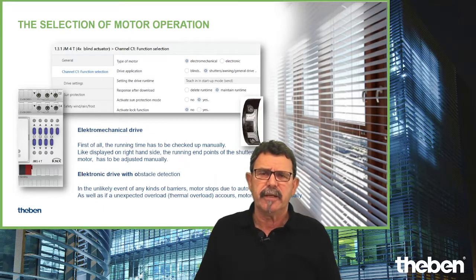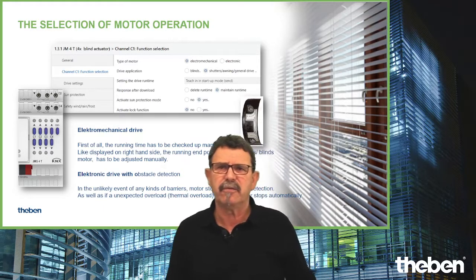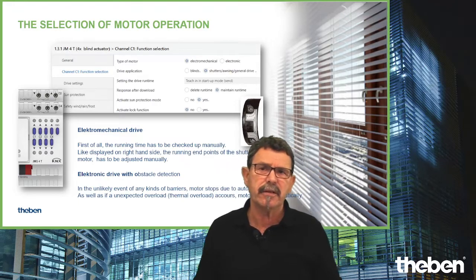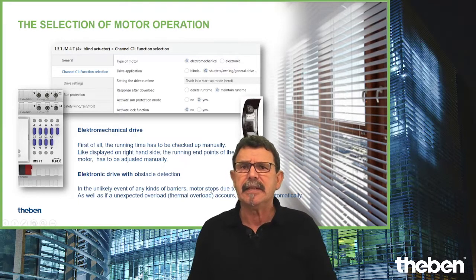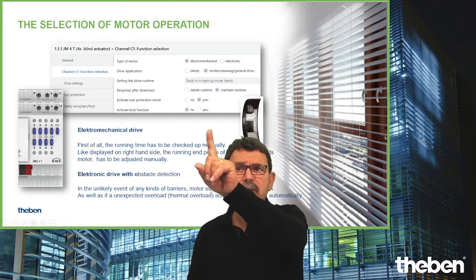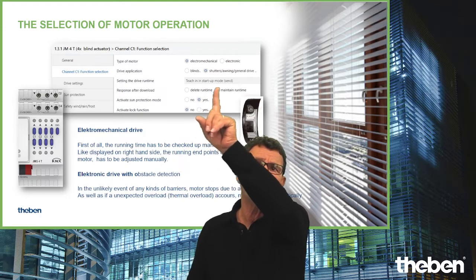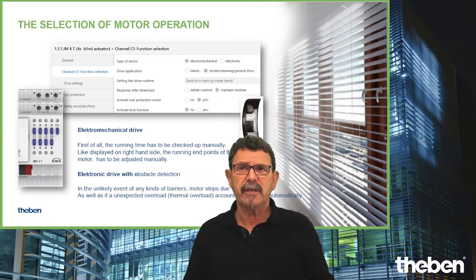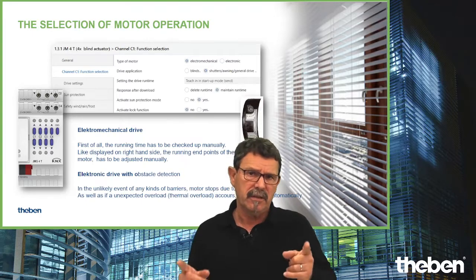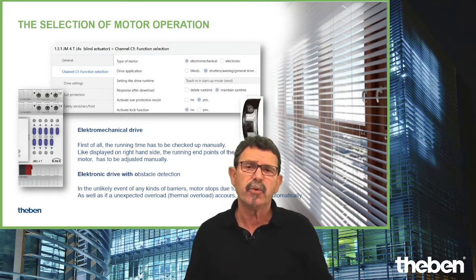A plus of 40% approximately is not unusual. And this has to be set, you see here in the application. So electromechanical drive or electronic drive, this you have to set up during the integration process.